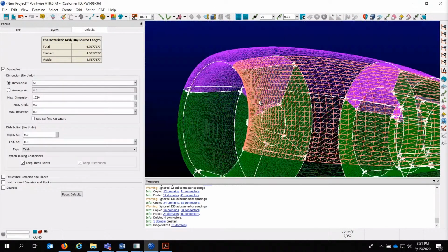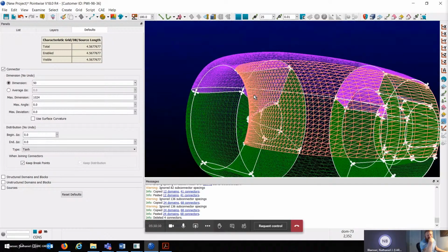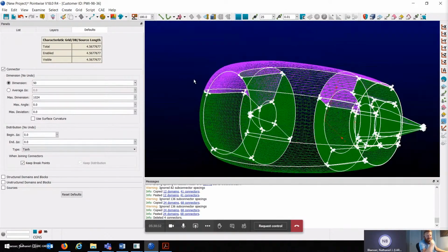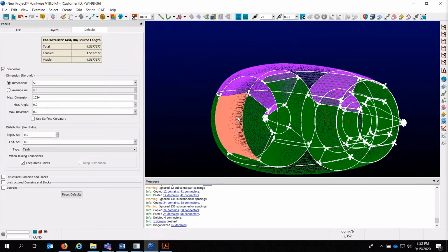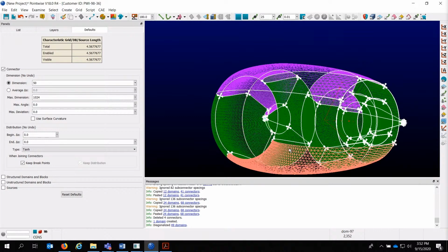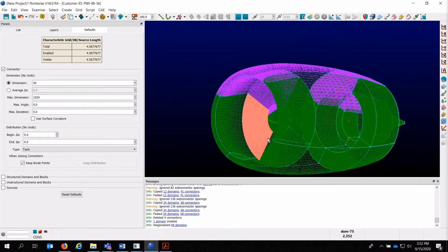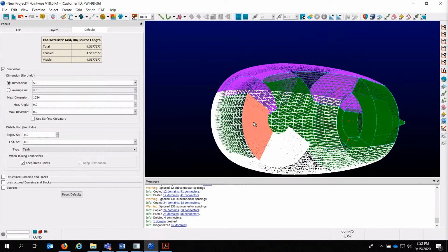You could also use T-Rex, and there are other features in Pointwise. It's a very powerful meshing program. But from here, yeah, you can grow your 3D mesh from this if you wanted to, using best practices. You can export this to Cart3D, apply your boundary conditions to these things, these patches here. There's your inlet, so on and so forth. But it works pretty well.